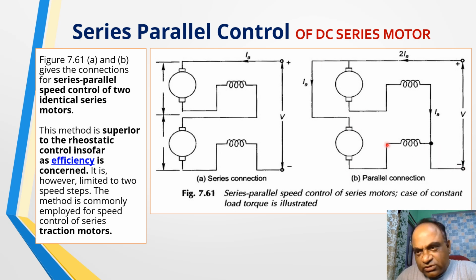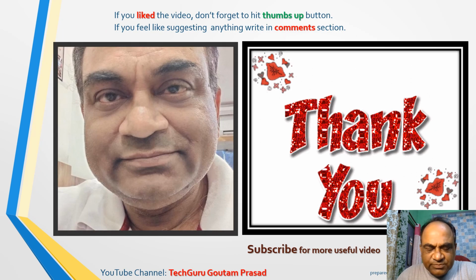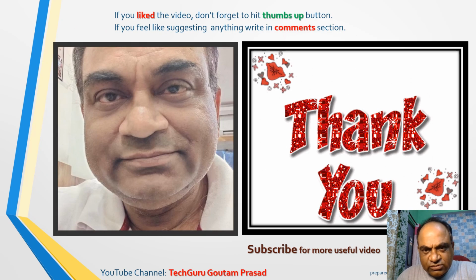So these two series motors have been directly connected across the supply, and in these two situations, the speed will be different. As the full voltage is appearing across the two motors here, the full torque will be developed here. But here, half of the voltage is appearing across this series motor and half across this series motor. So the torque will be halved in this case. So the speed will be halved in that case also.